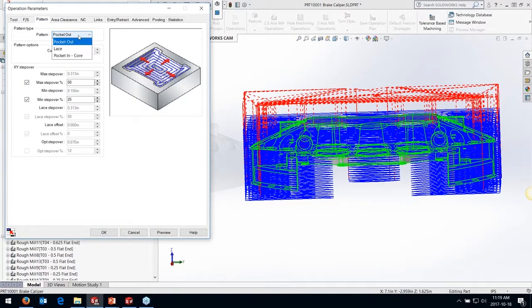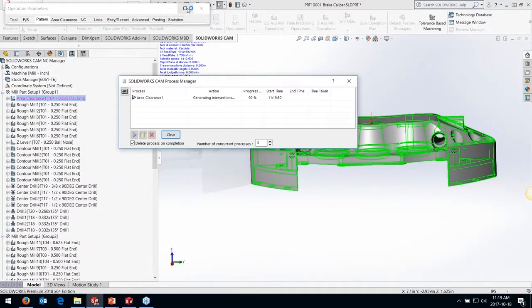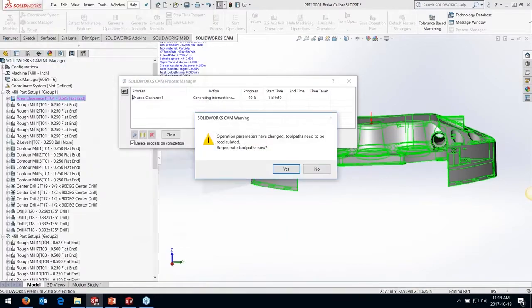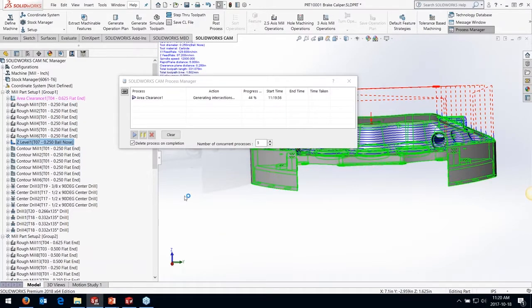And then I can control, do I want the tool order adjusting? So I can do it either way. I can do it by tool first or by operation. If you hit apply, it goes through, adjusts the order of the program down in the tree here, adjusts my tool order, and now I can go and generate that toolpath in here to basically program the roughers to clear that out.